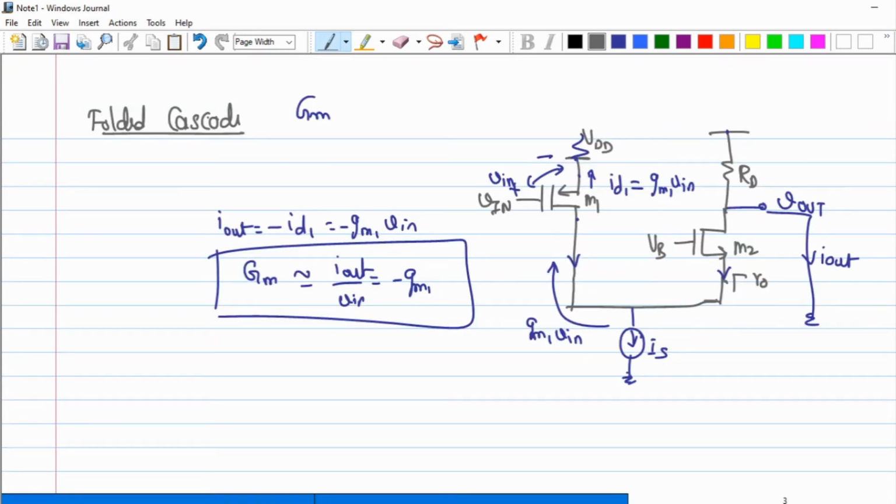Now, had we really addressed the issue of moving this value of VB? That is the next question, because the whole point of going from the cascode device to the folded cascode is that VB was being stuck between the values of VD2 and VD1. Now, with this circuit, can I make this VB go higher than the value of VD2?